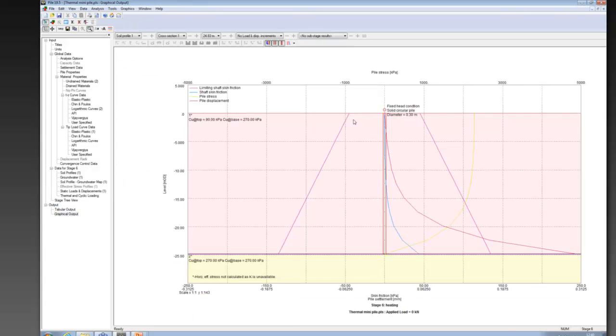just look at the same results that we looked at previously, now on the final heating stage, instead of the axial stress reducing to 0 at the top, it comes to a maximum where the limit, the kind of restricting effect of the structure is inducing quite a large axial stress. So at the top of the pile, we've got 0 displacement and therefore 0 mobilized shaft friction, and increasing displacement at depth. However, our maximum axial stress is now at the top of the pile.